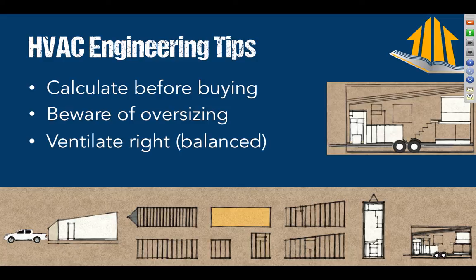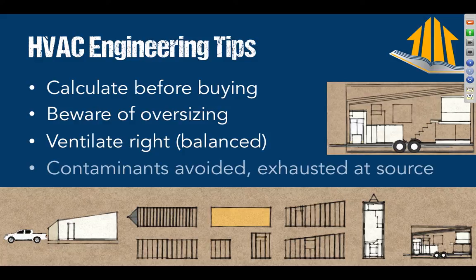Lastly, remember to ventilate. You need to provide exhaust, and also you need to remember that air will need to come in to replace that exhaust, and where is that going to be coming from, and are we going to have pressure problems? The most recent Building Forensics Mastermind webinar was all about a client who had chimney smell in his house, and it was because we had too much exhaust ventilation, and the biggest opening in the house was the chimney, and so of course the house was breathing in through the chimney, which is the opposite of what we want.